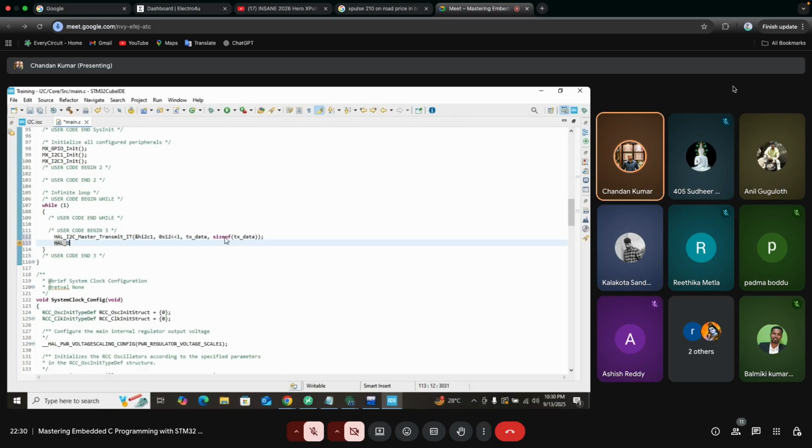Now I'll give some delay. Delay 1 second. Fine. What will this do? This will make my I2C1, that is master, transmit this TX data at this slave address. Okay. So my master code is completed here.